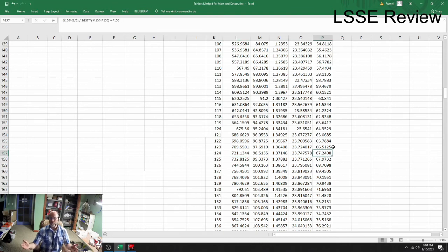I'm at 67 degrees. What did that demonstrate? I reduced the height of the ceiling. I went from about 4.5 meters, 15 feet, down to 10 feet, about 3 meters. It shows you how much faster it heats up the closer the ceiling is. That's another factor you have to take into consideration.